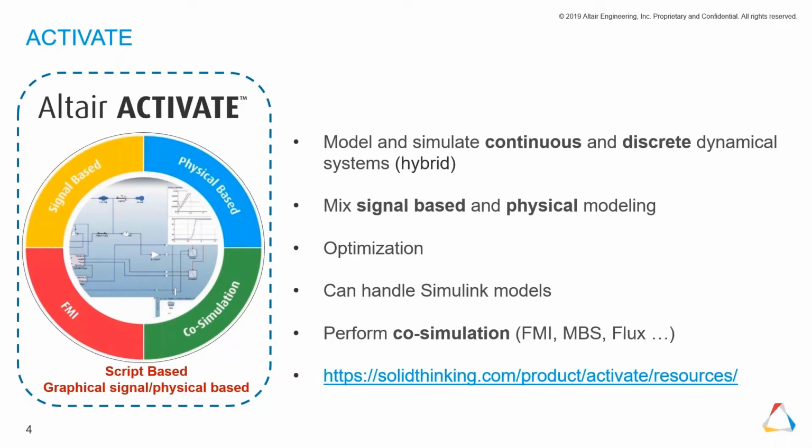Furthermore, you can perform co-simulations such as the Functional Mockup Interface. I think a few of you already heard about the FMI. It's a standard where you can exchange models from one simulation tool to another simulation tool and vice versa. There are two different kinds of FMIs. One is the model exchange, where just the model is converted to a package. And then there's also the co-simulation, where the solver is also put in that package.